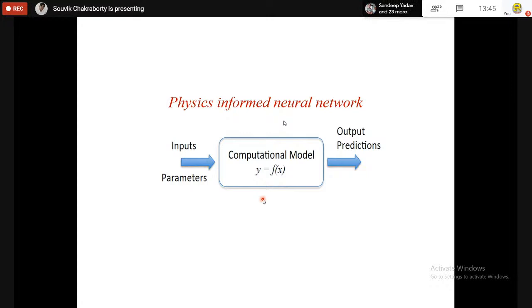Then you write it for y and z, and that is your governing equation. So when you're using finite element method in Abaqus or ANSYS, that is the equation that you are solving, knowingly or unknowingly. That equation is discretized, and you get Ku equal to F. And from that linear equation, you basically find out u by K inverse F.